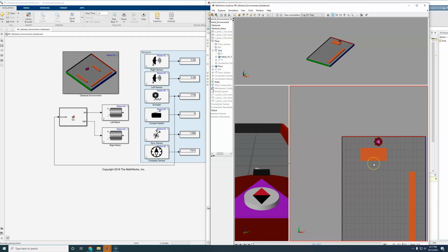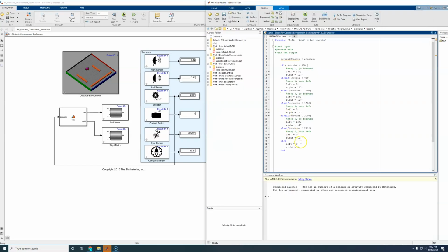Back on the downwind leg. Good. It cleared the corner. Oh, we overturned a little bit. Hitting that wall really stopped our turn. So now we got off that wall. We know that we're overturning just a little bit. So let's just knock 2 off of that, and then let's see if we can go ahead and calculate our forward.